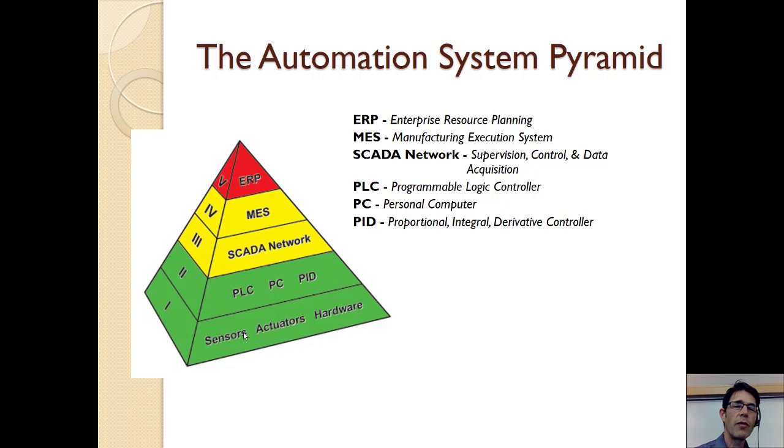It's taking feedback from the hardware, from a sensor, and then delivering commands back out to the hardware. So there's a lot of communication. Most of the wiring is done between these two layers, the sensors and the actuators and the controller. Most of what we're going to be doing in the course is going to be focused on these two layers because that's where most of the major problems, the maintenance, the alignments, sensors, electrical problems, generally happen in these two layers.